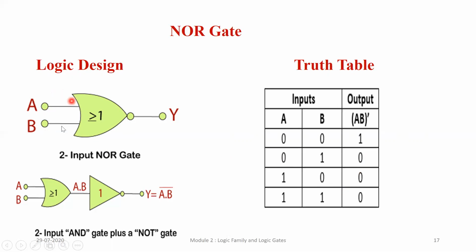Then you give both high. You apply 5 volt over here and 5 volt over here. Just using a wire you will connect, because already 5 volt you have given somewhere in the IC. The pin numbers will be there, because as I said, in one IC there will be 4 gates present. Each gate needs 3 pins, so 3 fours are 12, and then one for VCC and one for ground. So it will be a 14 pin IC. This is how you verify the truth table.